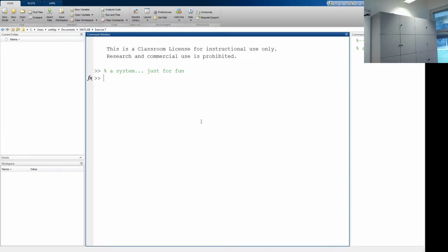The closer these are, the more ringing you have. This is the kind of fundamental frequency of the system. And then let me kill the ringing somewhere there. Say plus minus pi over 3 angle, and is this pi over 12? Maybe. This distance is about 0.2. Let's see what happens.